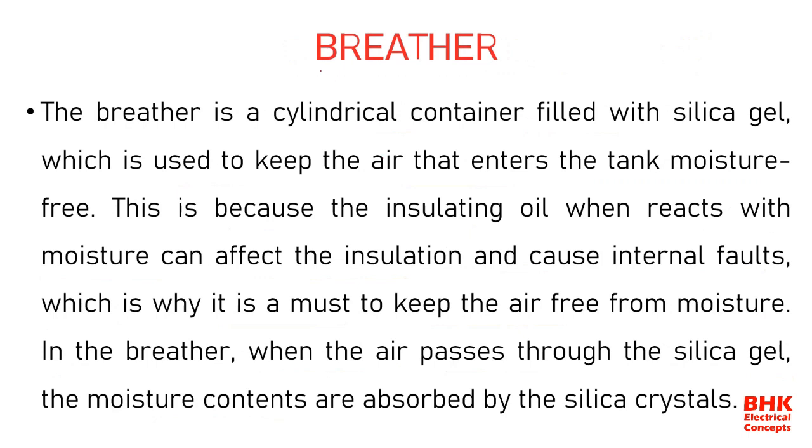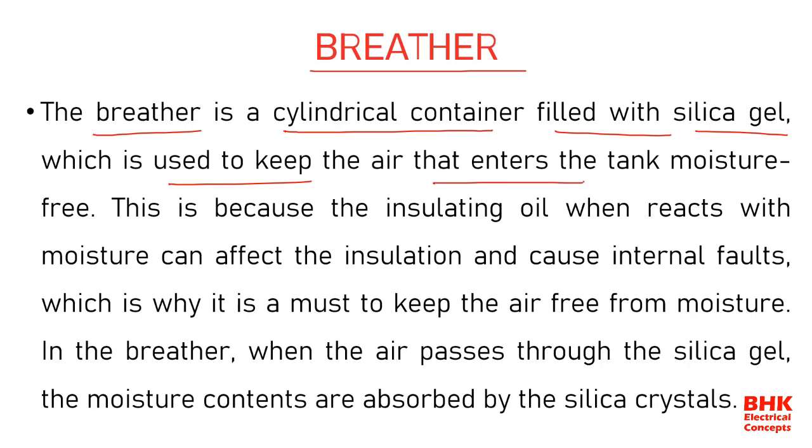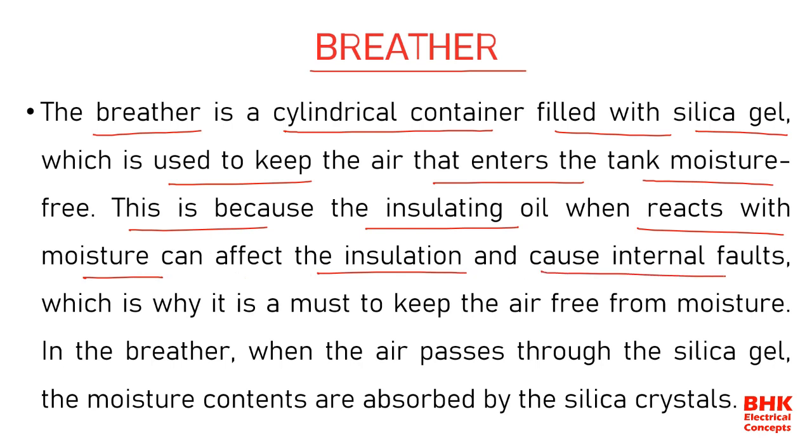Now coming to the breather. The breather is a cylindrical container filled with silica gel, which is used to keep the air that enters the tank moisture free. This is because the insulating oil, when it reacts with moisture, can affect the insulation and cause internal faults, which is why it is a must to keep the air free from moisture.